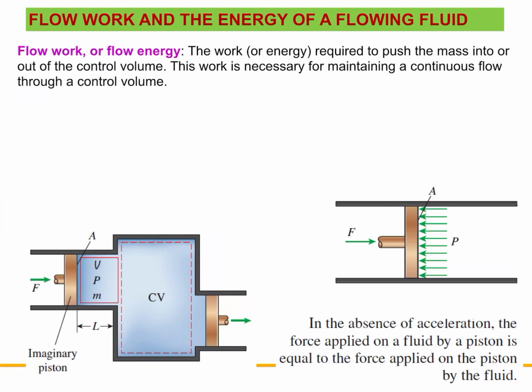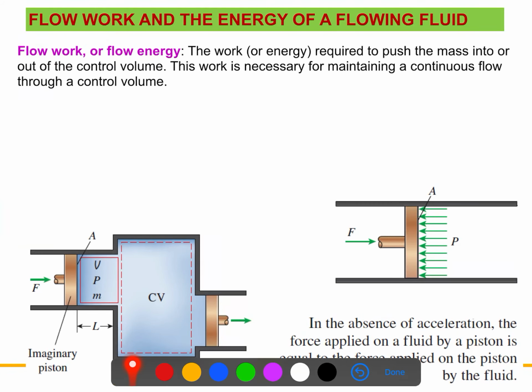In this video, I'm going to discuss flow work and the energy of a flowing fluid. At first, we'll try to understand what actually the flow work is. What is flow work? This is the work or energy that we need to push the mass into the system or from the system, so into the control volume or from the control volume out of the system.